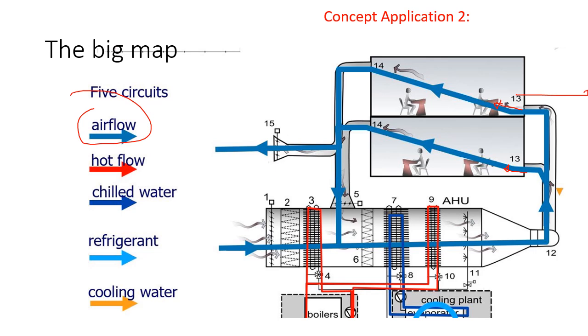In the winter scenario, the air is heated by the preheater, and then this cooling coil is off, and the reheater heats again, and the air is driven by the fan into the room at a higher temperature, so it can drop in temperature and release heat into the room to compensate for the heat loss to the outdoor environment.